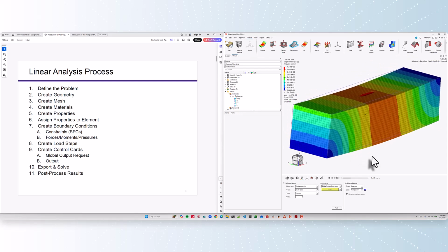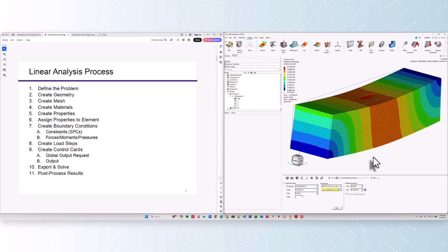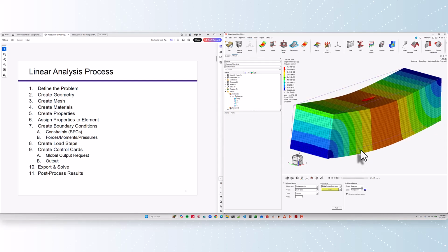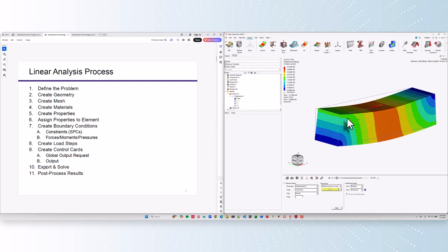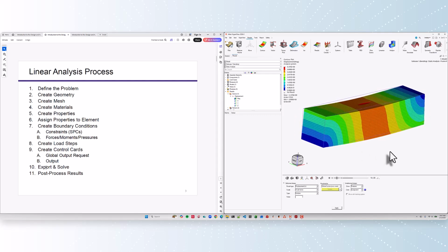That it's just Z restraint plus rigid body, and everything I did was just rigid body. So the X and the Y was just rigid body. It wasn't constraining anything in any other direction. You would see it pick up a deformation or a concentration if you constrained it in anything other than just rigid body.